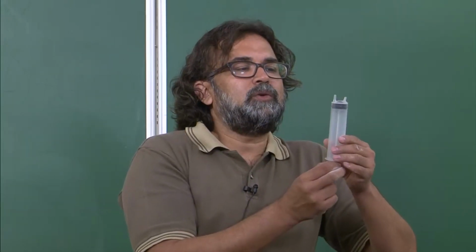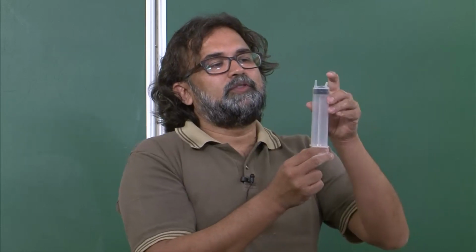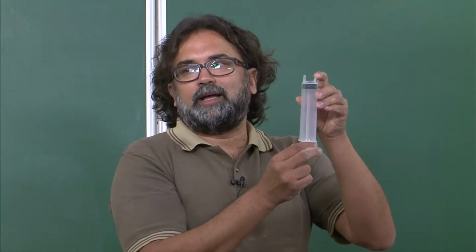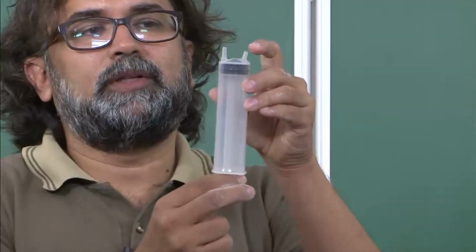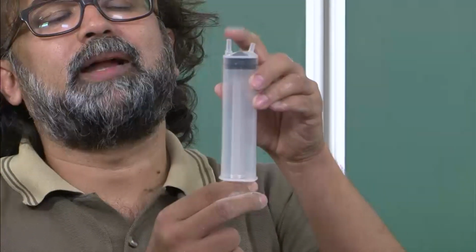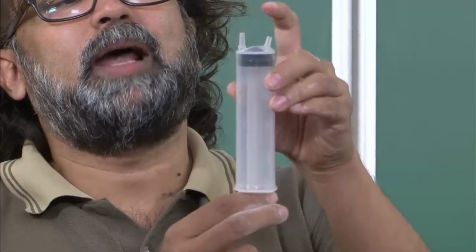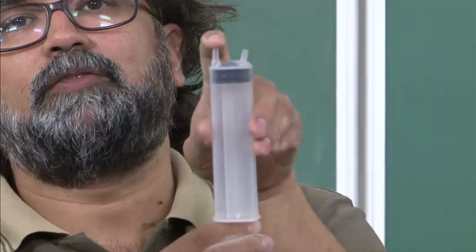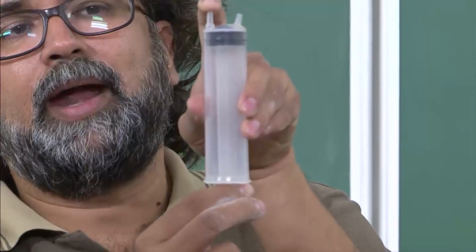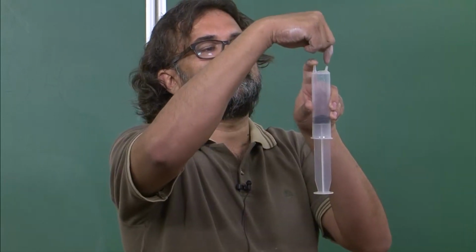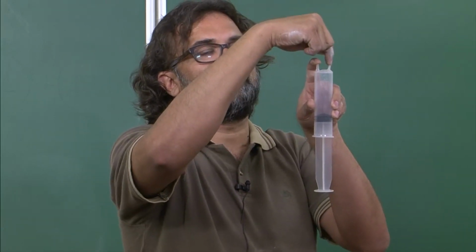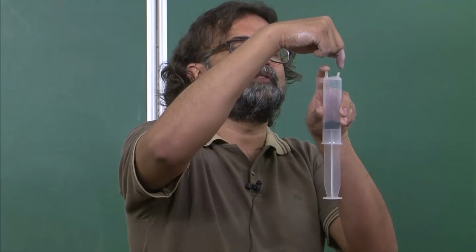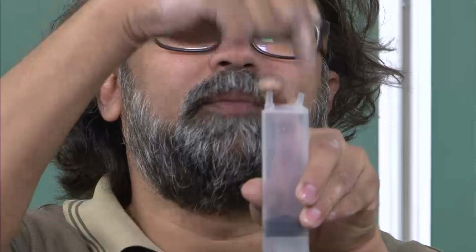Okay. So when you are sucking in, let us say this one is called the inlet port and the larger one is the exhaust port. Then when I have to suck this charge inside, I need to close the exhaust valve. So the exhaust valve is closed and my piston is going from the top dead center to the bottom dead center, and in the process it is sucking air-fuel mixture from this valve. This valve will be open and the air-fuel mixture will go in.